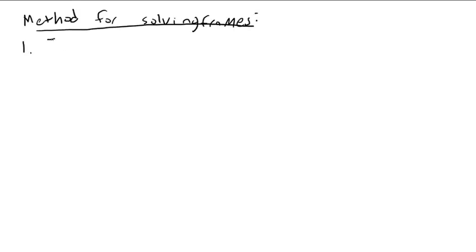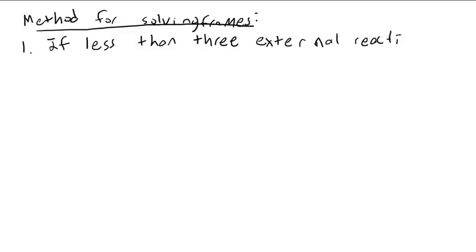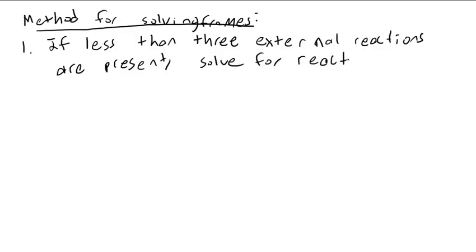One, if less than 3 external reactions are present, solve for reactions treating the frame as a rigid body.